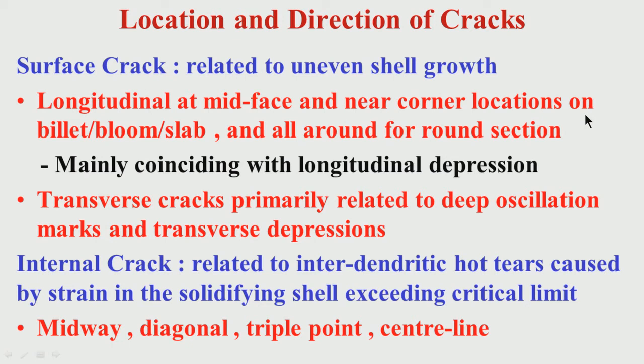That means if the surface is uneven, lot of depression is there, so grain sizes are coarse. So, if the grain sizes are coarse, grain boundary areas are relatively less. So, even at low temperature, that means around 600 to 700, there is a possibility of formation of nitrides of aluminum, niobium. So, those will try to form at the relatively less grain boundary area.